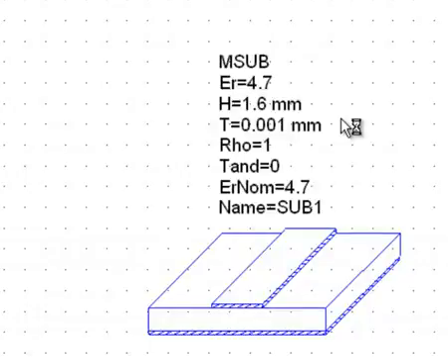Rho is the bulk resistivity of the metal compared to gold. We'll leave it to 1. It won't matter a great deal. The loss tangent can be 0. As we've seen, this parameter also does not alter the characteristic impedance of the line by a great deal. So we've got pretty much all the parameters that we needed.